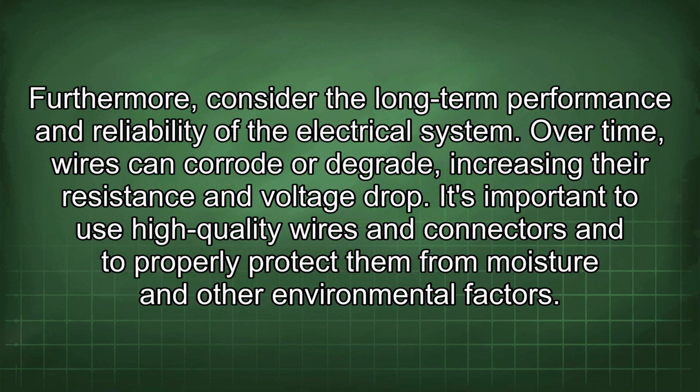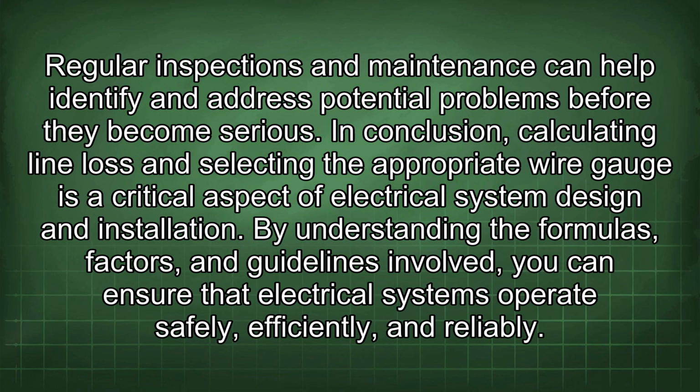Furthermore, consider the long-term performance and reliability of the electrical system. Over time, wires can corrode or degrade, increasing their resistance and voltage drop. It's important to use high-quality wires and connectors and to properly protect them from moisture and other environmental factors. Regular inspections and maintenance can help identify and address potential problems before they become serious.